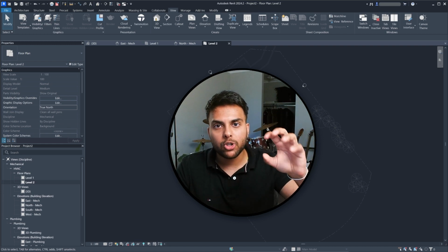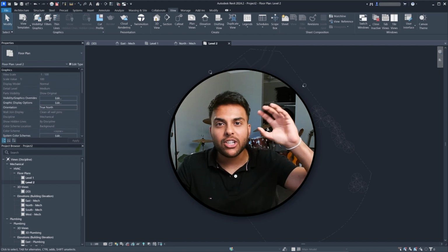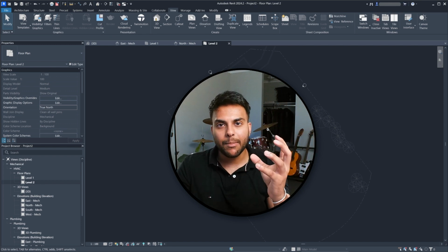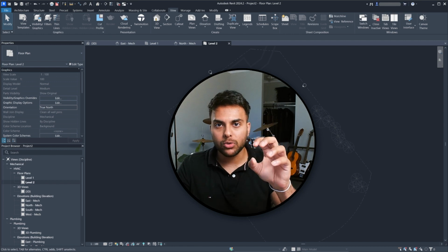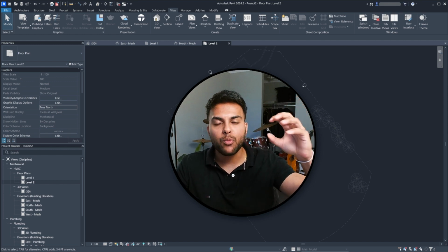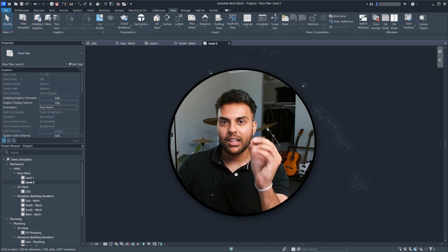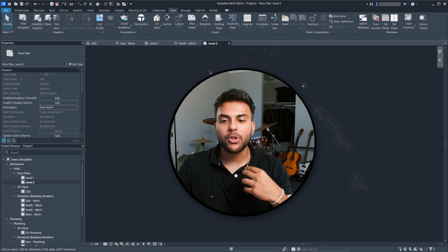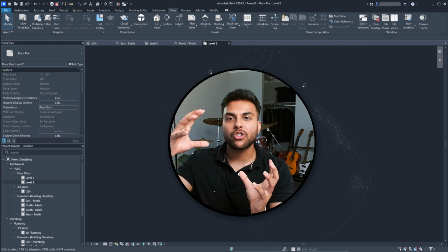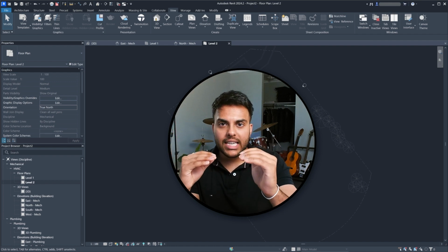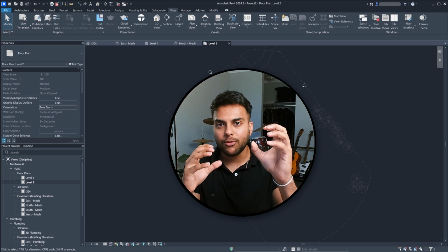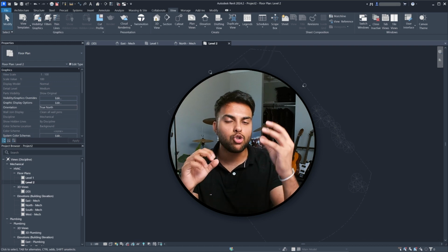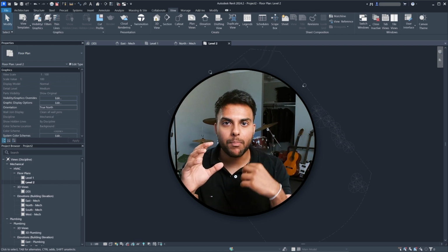So we need to be able to create view templates and change our visibility graphics, override things so that we can actually clean the model and only have the essentials from these other Revit links, and we only have the essentials like grid lines, elevations, and all these things which are necessary from our template, because then we can actually start modeling while seeing the 3D views, but the 3D views of the other architects and structure and consultants don't actually get in the way when we model, right?